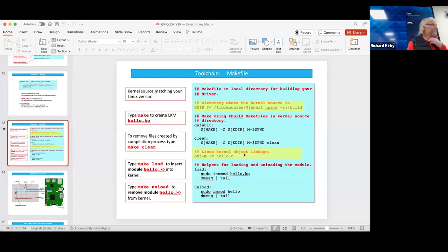And when you know that address, you've understood how the hardware operates, you can just write straight to those. Yeah, that's right. They've got a fairly complex GPIO chip, which is in the address space of the ARM processor. So you go through the data sheet, you look where it is in the address space, and then you write that in your GPIO functions.